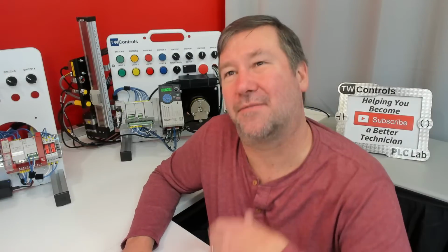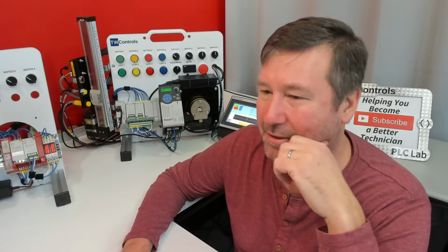But as far as the fault handler goes, my philosophy is if you can handle the fault, maybe you can gather information and hopefully have some type of info to help us troubleshoot it. The one I don't like that a lot of people do is they want to clear the fault on power up. The next thing you know, people are always like, well, cycle power, that'll clear that fault, and next thing they're cycling power every time something's wrong with the machine. So overall, I will probably do a video on it eventually, but yeah, it's not real exciting to me.